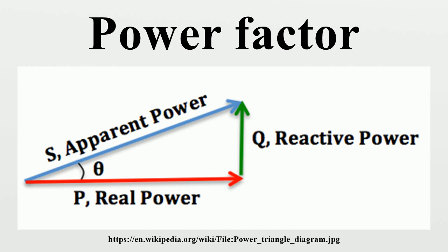Real power is the capacity of the circuit for performing work in a particular time. Apparent power is the product of the current and voltage of the circuit, due to energy stored in the load and returned to the source. A negative power factor occurs when the device generates power, which then flows back towards the source, which is normally considered the generator. In an electric power system, a load with a low power factor draws more current than a load with a high power factor for the same amount of useful power transferred.